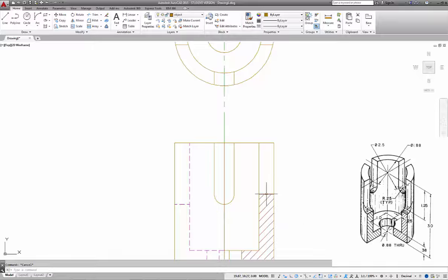We can do the same thing now with this side. So I'm going to grip this line, grip the middle, come over here, pick this end point, bring it straight across, find that intersection again, 0 and 270. Perfect, that's a 90-degree intersection. Left mouse click, hold it. Those section lines just updated automatically, didn't they? How cool is that? If you change that surface area, or you change that boundary, because we gripped and moved that boundary of that sectioned area, it will automatically update.